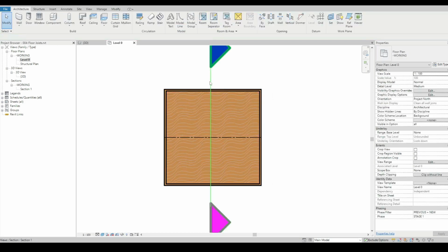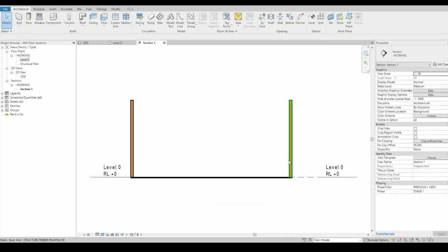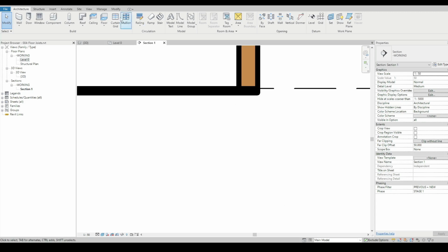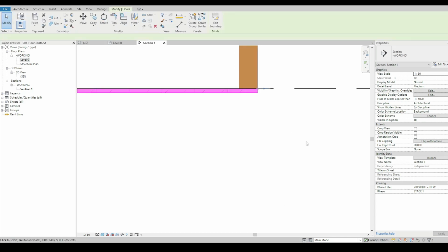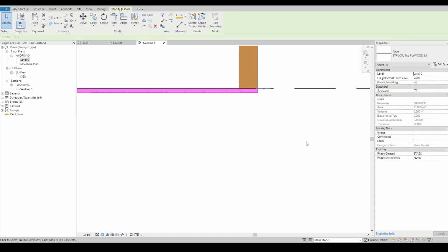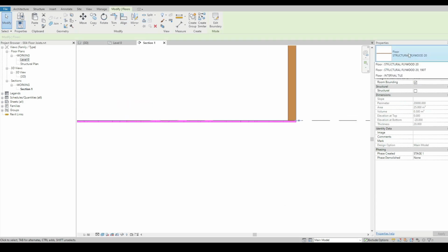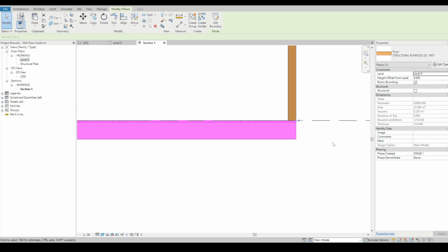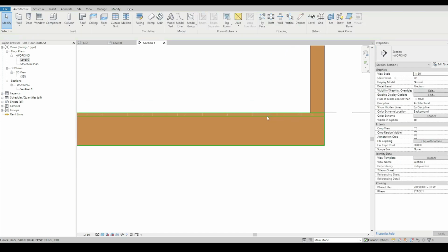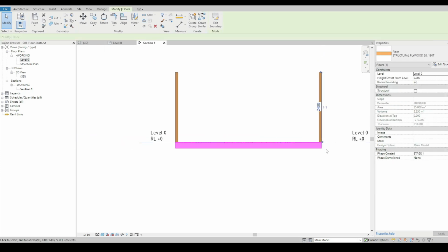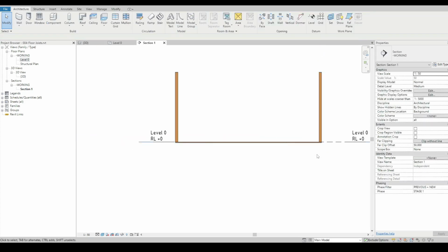So what have I made? I've in essence made just a thin little flooring element which is about 20mm thick. Now I could, if I wanted to, make this floor the flooring and the floor joist as one element. That is one method of doing it, but the one I'm also going to show you is how to do it using multiple elements.